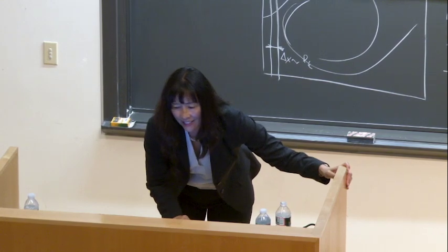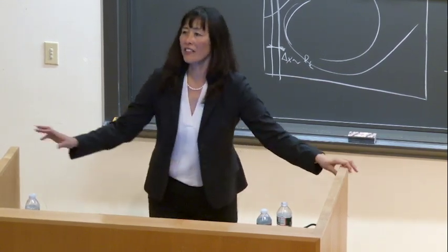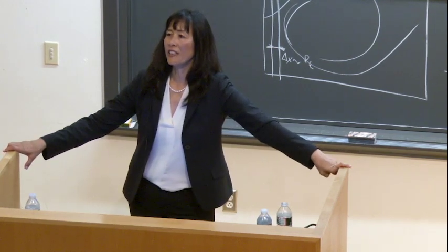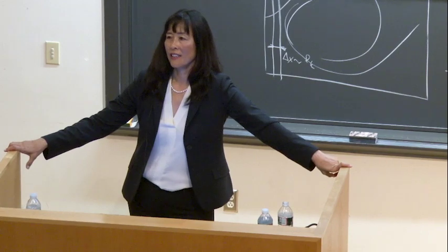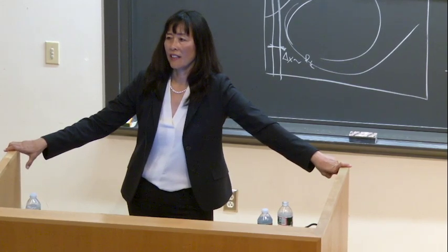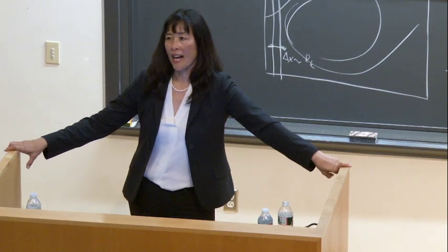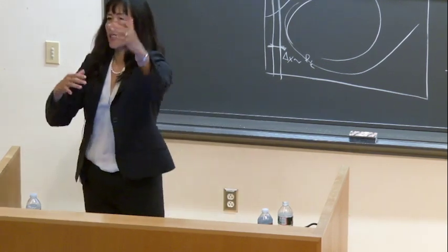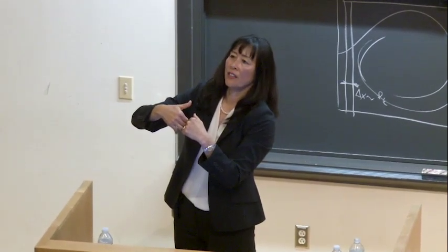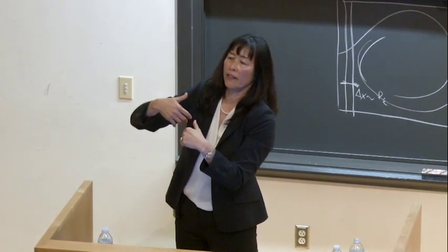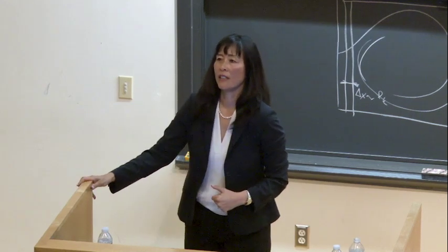What's the order of the discretization? The order? Yeah. It's 8th order centered finite difference. Is it the same stencils you have in S3D? It is. It's exactly S3D, but multiple blocks, so they have interior boundary conditions between the blocks. And right now we're requiring the mesh to line up between the blocks.